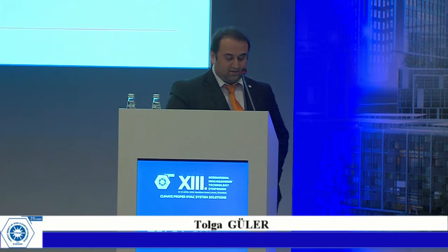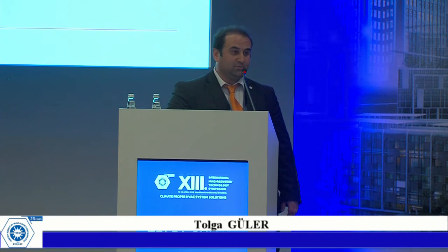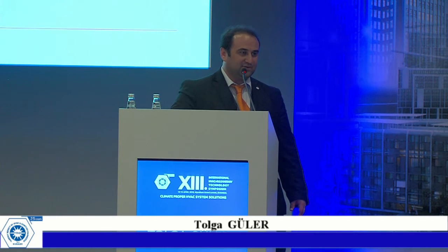I want to say something more. If we are interested in pressure drops only in our design, we can use the porous definition. If we want more details in an acceptable time, we can use gap modeling. If we have enough computational resources and enough time, and we want to see every detail, we can use grid modeling.